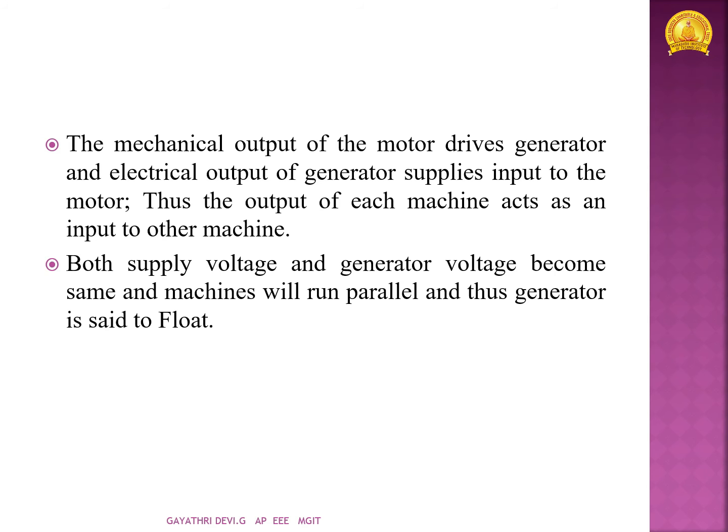The same thing is explained once more here. The mechanical output of the motor drives the generator, and the electrical output of the generator supplies input to the motor. Thus the output of each machine acts as an input to the other machine. That means the motor as well as the generator act equally as input and output to both the machines. This process is known as regeneration. Because of this concept, our test is also known as a regenerative test.